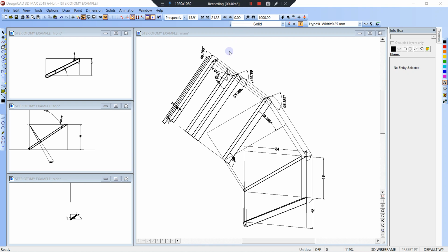Oh, I was going to stop it, but I think I mentioned it. If you put this in a cradle or in a vise or make a laser template or something like that, you could tack weld it to the bandsaw, and then you could cut this with a non-tilting bandsaw, and you would get that proper compound angle. And that's what I wanted to mention before I cut out.